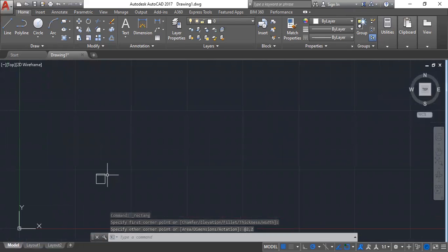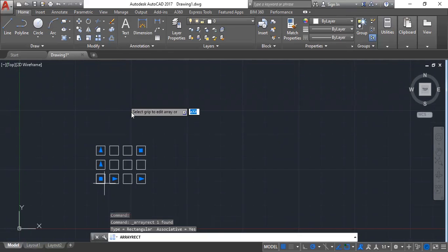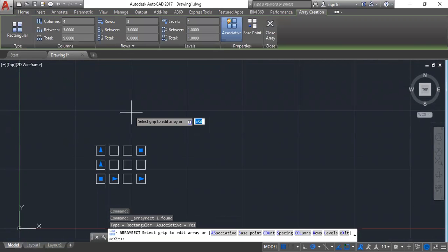Now, let's say, for example, you want to duplicate this square to come up with maybe 100 copies, 1,000 copies, 1,000,000 copies, and so on and so forth. So what you do, you click on the square or click on the shape to select it. Then up here, you select what you call the rectangular array. Once you click on the array, as you can see, automatically, it's going to give you some copies.